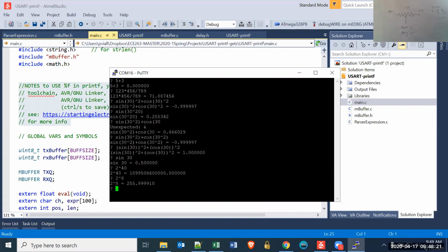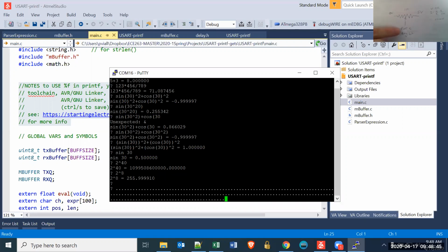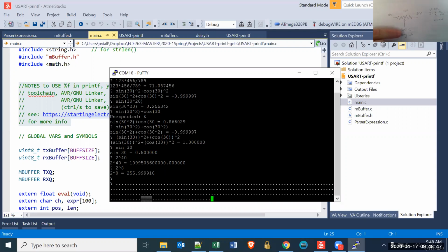The special thing about these potentiometers, or volume controls, is there is a third thing known as a wiper arm, which can slide along this coil of wire. If I slide this third arm, this wiper arm, all the way up to 5 volts, on the wiper arm I'm going to get 5 volts. If I slide it all the way over to the 0 side, I'm going to get 0 volts on that wiper arm. If I'm right in the middle, I get about 2.5 volts because there's a pretty linear drop as I go from the 5 volts to the 0 volts across that resistor.